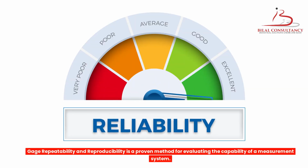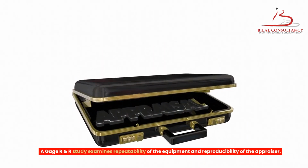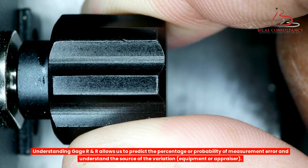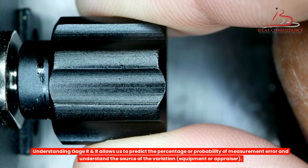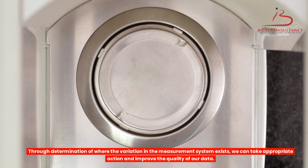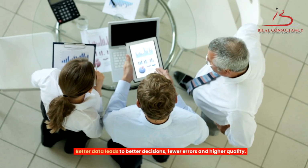Gauge repeatability and reproducibility is a proven method for evaluating the capability of a measurement system. A GageRnR study examines repeatability of the equipment and reproducibility of the appraiser. Understanding GageRnR allows us to predict the percentage or probability of measurement error and understand the source of the variation, equipment or appraiser. Through determination of where the variation in the measurement system exists, we can take appropriate action and improve the quality of our data. Better data leads to better decisions, fewer errors and higher quality.